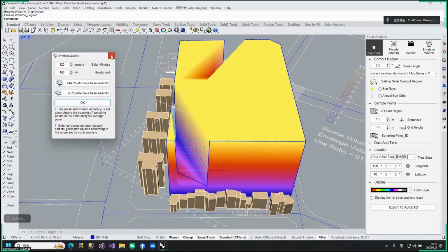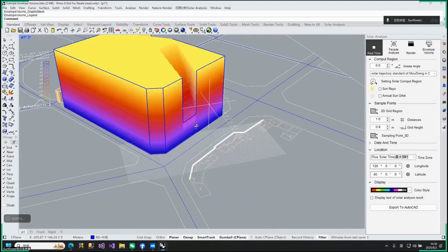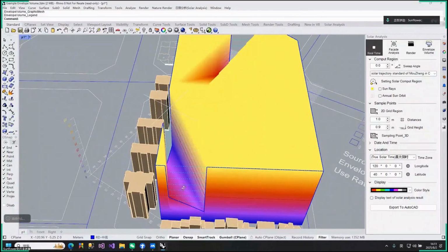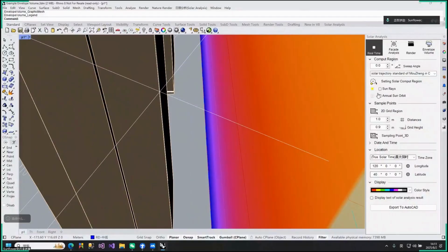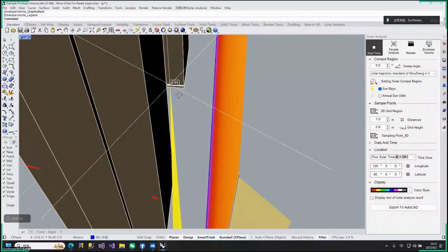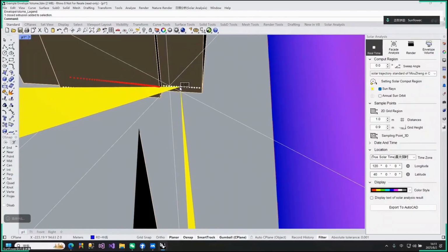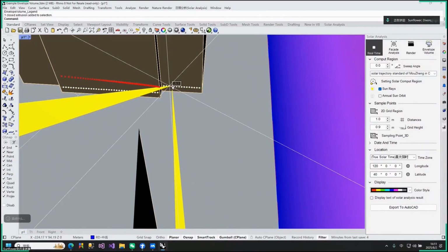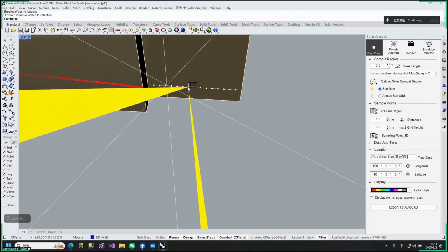Once the calculation is complete, the software generates this envelope. It's like a precisely cut volume telling you that you shouldn't build anything outside of it or you'll block the neighbors. This boundary is pushed to the absolute limit. I'll turn on the solar analysis so you can see. When I move the mouse along the boundary of this envelope, the sample point's sun duration is exactly 2 hours. If I move the sample point just a little bit outside, its sun duration drops below 2 hours.